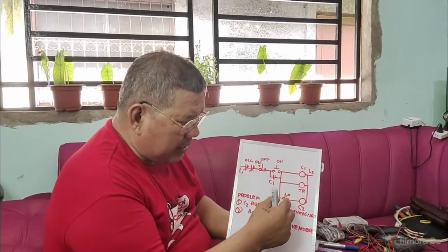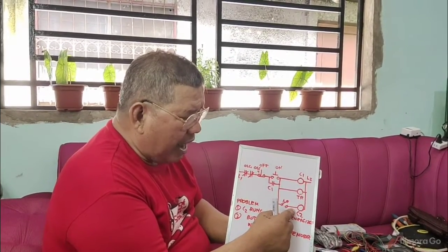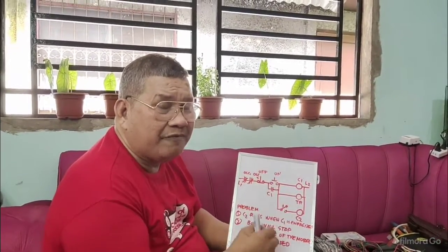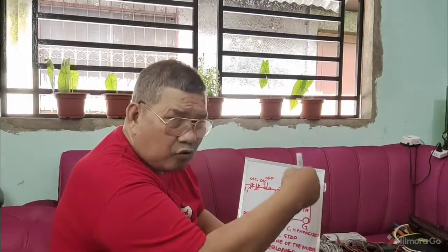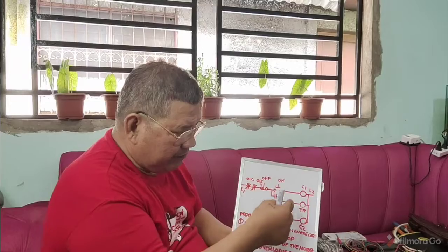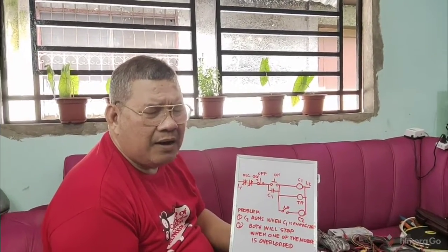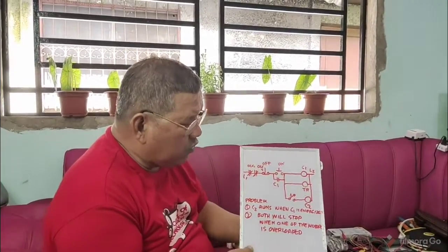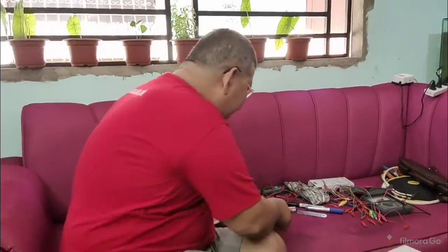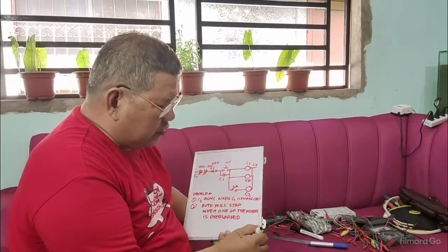That when motor number 2 or conveyor number 2 is already running, then automatically the time delay relay is also disconnected from the circuit. But both conveyors are already running. What we preserve is the life of your time delay relay. How would you change this? Simple, no? Very simple. So you are going to have this connection.